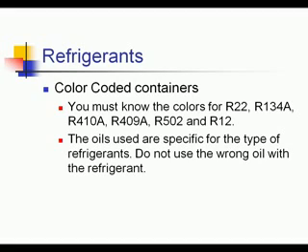Now, along with the refrigerants, you have refrigeration oil. They provide the lubrication for the compressors. They're mixed into the system. They're going to go around with the refrigerant. And they will eventually make it back to the compressor, work their way through the compressor, and again go through the cycle. You have polyester oil, alkylbenzene oil. These are synthetic oils.